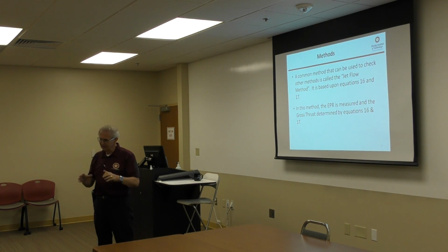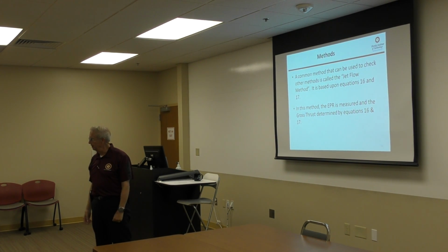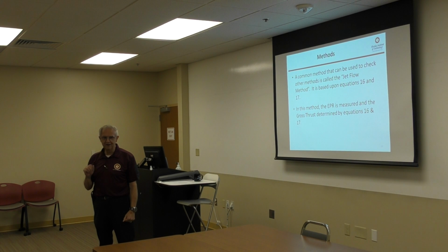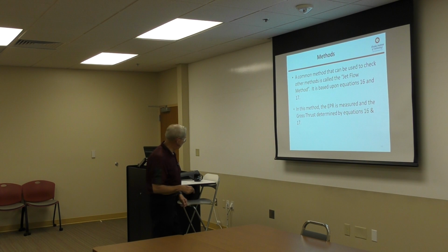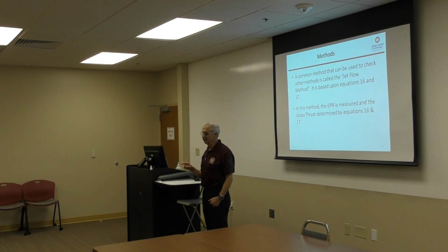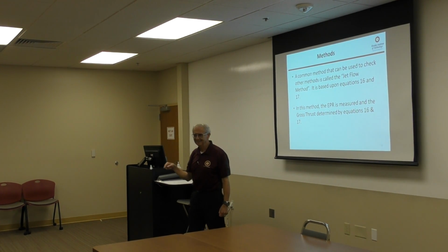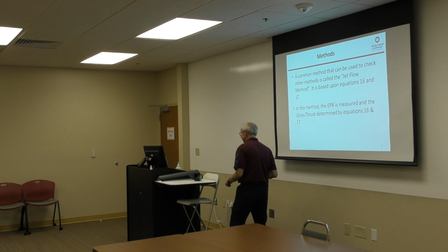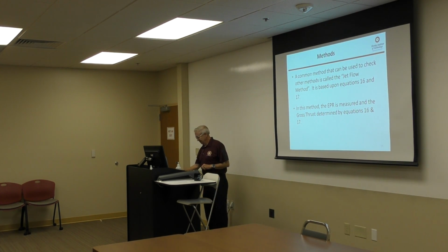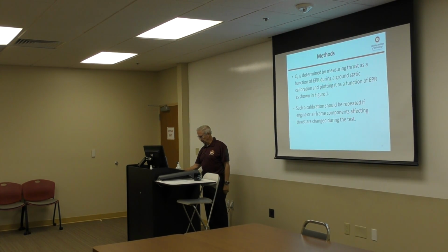And we tie it down to this stand, and this stand is movable and has strain gauges, which we can tell how much force is being generated. And we run it at various power settings. And so we know what the left-hand side of that equation is then. We have the right-hand side except for the thrust coefficient, right? And the difference between the two becomes our thrust coefficient. Now, everybody doesn't have one of those.